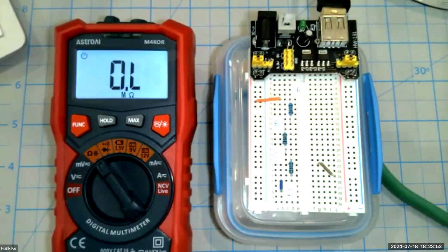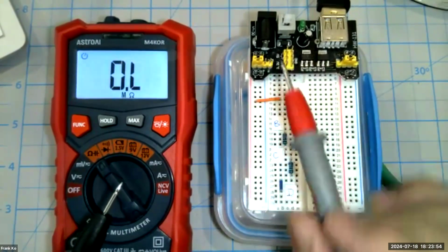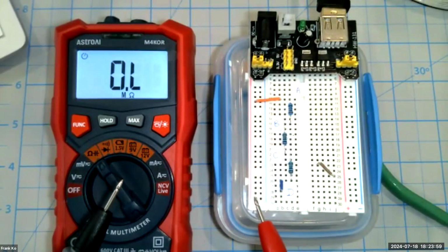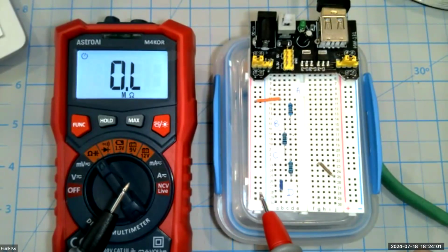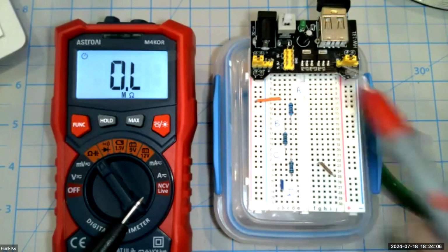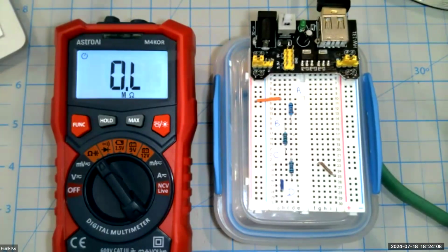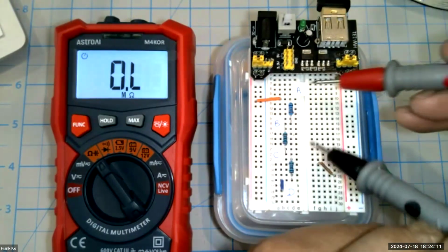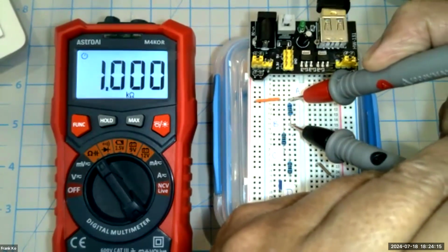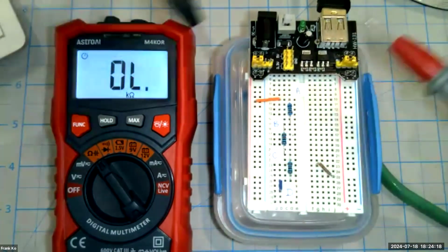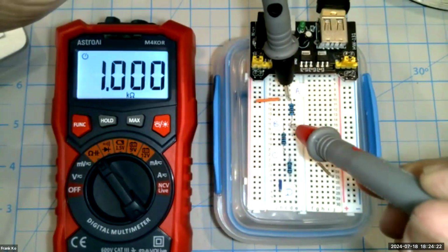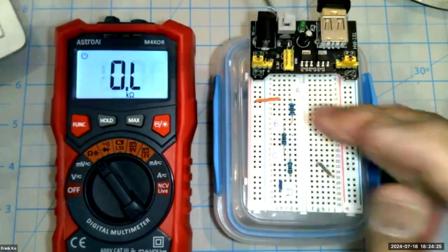And so the power supply is still on the board. It's not energized, but because I don't have a return path at the bottom of the resistor to the negative side of the power supply, I do not have a connection back to the power supply. So now the circuit is independent and a happy camper. So I'm going to go and measure. This should be a nice 1 kilo ohm. And it doesn't matter, if you recall with the resistor, which polarity we use, because resistors are not polarized. That's a nice 1K ohm resistor.